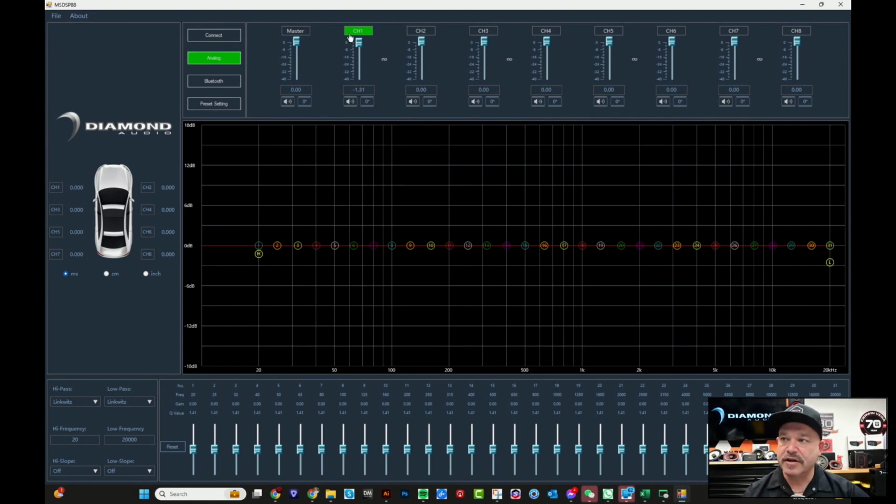And then let's say we're going to adjust channel 1. Let's say that this is going to be our tweeter crossover. So we can do high pass, low pass, band pass, whatever we need. We're going to cross these over at 5K, so we can type in 5,000 hertz right here. And then we can pick our crossover slope. Let's go with a 12 dB slope, and then we'll hit enter. And now you can see in the graph, we have a 12 dB slope at 5,000.